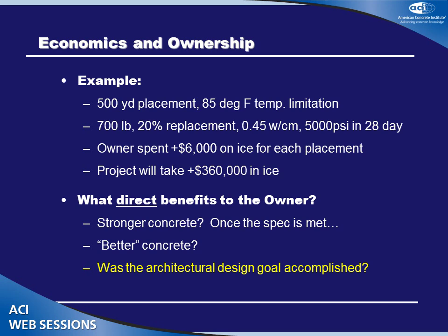Won't get into that one a little bit, but my point is, in this particular case, we spent an inordinate amount of money on this project to achieve a temperature requirement in hot weather, and we weren't really sure if we met the design goal here other than that it looked the way we thought it would, because it matched the test panel. Interestingly, though, when we made the test panel, we didn't use ice and we didn't use 85 degrees. We just cast the test panel. So somebody say, well, see, the ice worked. Well, I would like to say I probably could have done all of this and not had to spend the money as well, particularly when I'm rejecting trucks because I don't have my ice fully melted.